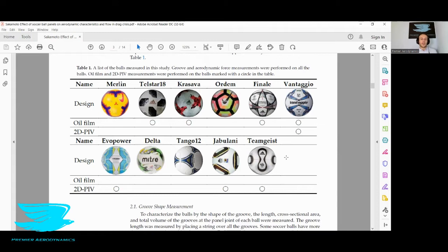And for a soccer ball, you have effectively 3 different components of drag. There's the typical skin friction drag, which everyone knows. There's the pressure drag, which is effectively a pressure differential from the front to the back, which creates an overall force. And then there's effectively a vortex drag. And depending on which field you're in, that can be called induced drag or vortex drag. This drag is just drag that's created, that energy is used to create vorticity. And there are quite a few vortices that come off of the soccer balls.